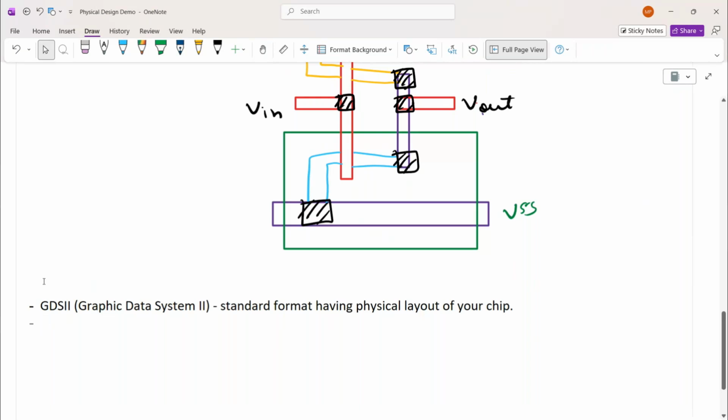So the foundry will take this GDS2 and manufacture it. It is going to have the information about what is the structure, what is the interconnection, and what all cells are there. There will be thousands of cells, and they are connected to each other; those are called interconnect. The connection will be using metal, right? We use wire over here, a big track, but there it will be a metal layer which they lay down.